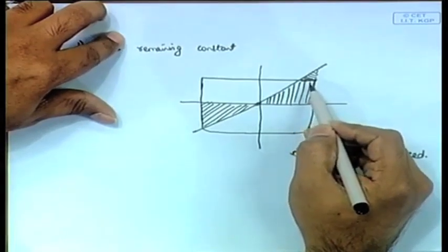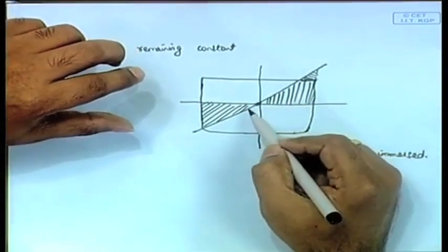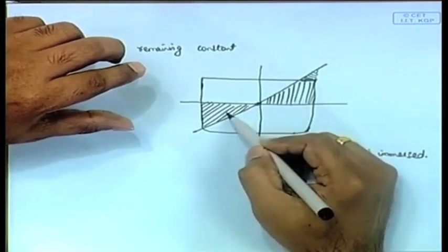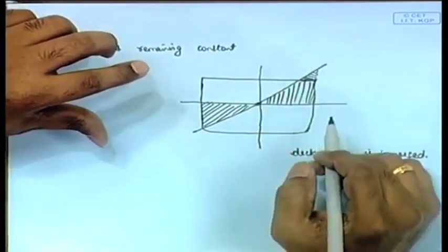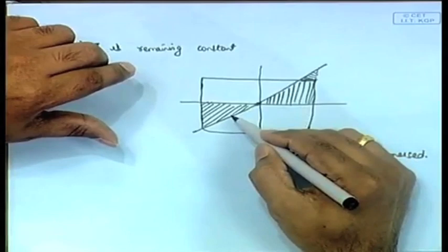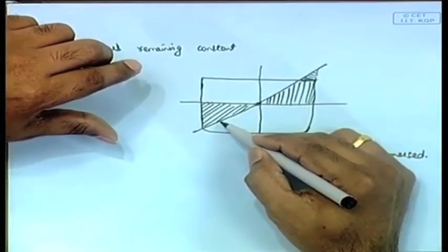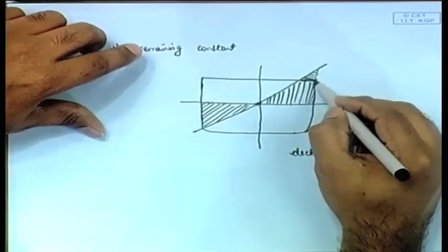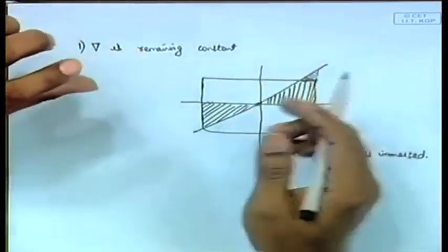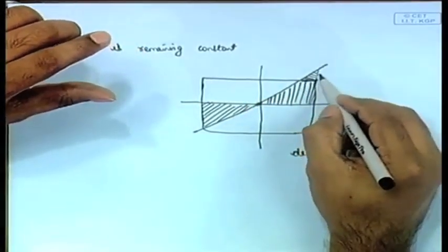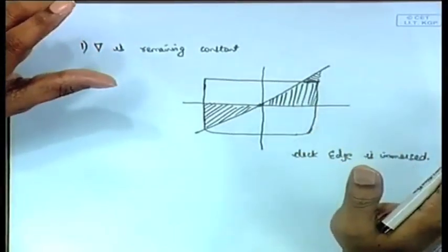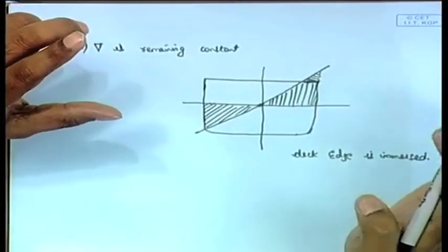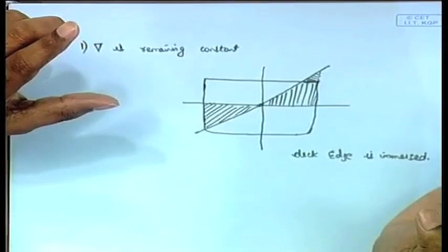There is a difference in volume between the side immersed and the side emerged. More volume has emerged, whereas less volume has gone in, because this volume is actually air, it is not water when it goes in. So, this is not the ship. So, that much volume is lost. So, what do we have? We have the volume immersed not equal to the volume emerged.